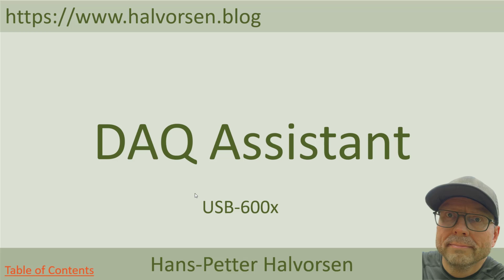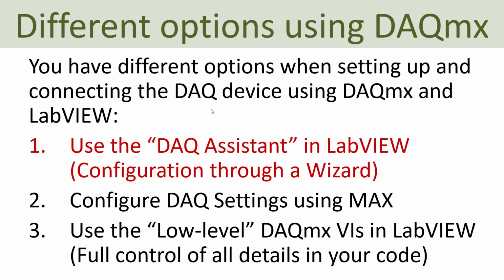So in part 1 I want to show how you can use the DAQ assistant. So basically we have 3 different options. I guess you have also more than 3 options, but in this video I will show 3 different options. So the first option I will show now is how to use the DAQ assistant in LabVIEW, and then you will use a wizard in order to configure and set up your hardware, and then you can easily use the DAQ assistant to read data from your DAQ device.